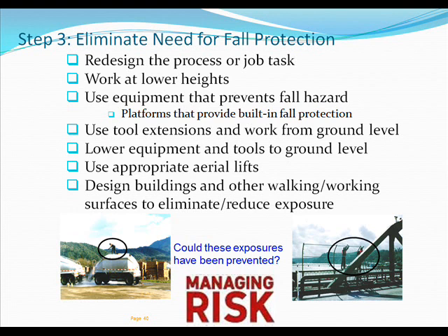Eliminate. Work from ground, walls, enclosures, covers. Prevent. Railings, aerial lifts, fences, barricades, and parapets. Arrest. Personal fall arrest systems, personal fall restraint systems, nets, positioning devices, roof brackets, slide guards. Control. Safety monitors, warning lines, controlling decking zones.